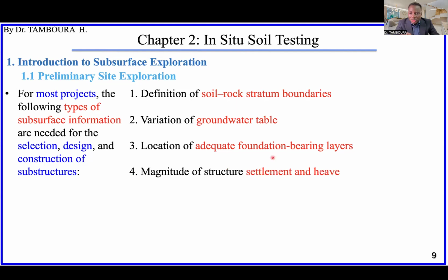And for magnitude of structure settlement and heave, if you check the soil, for example, if you have clay in place, you may have to be worried about heave. Depending on the soil you have, you may judge what can be the magnitude, the amount of settlement or heave you can expect. And also sometimes we need to do the dewatering.